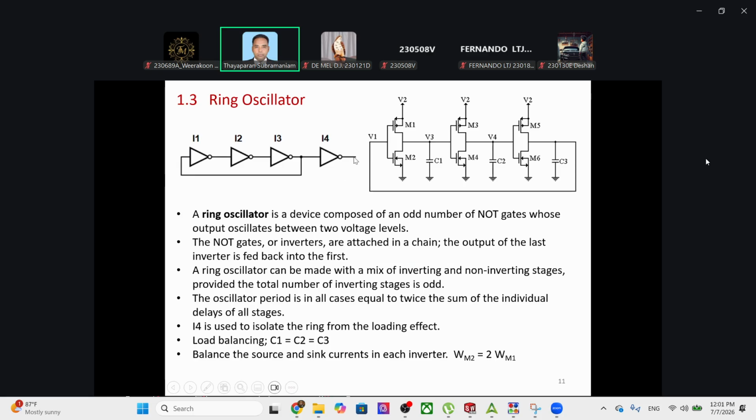Okay, there are some design challenges. We are at the very beginning, right? However, the first step is to bring the silicon out and measure it. It may be successful, may not be successful. If we are successful, that's fine. As long as it is switching, we can say the clock is working. Then what is the next question? Quality of the clock. How much jitter do we have? What is the duty cycle variation? We can measure it in the lab, right?